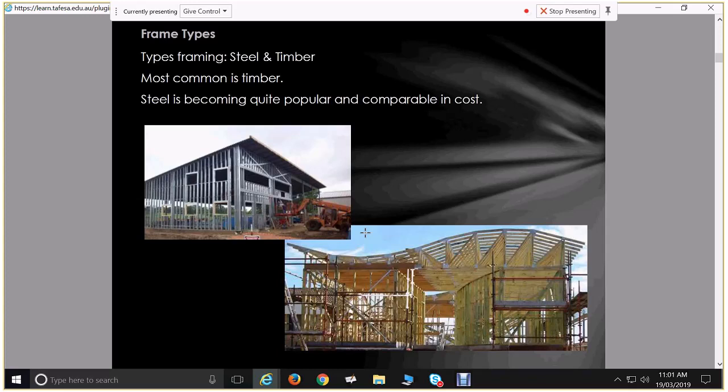So if we're prefabricating stuff in a factory, one of the limitations is we can't and we shouldn't go making modification decisions on site. Sometimes we can. And also it has to be transported. So the size of these elements, and then also they have to be lifted. If we're building a wall frame on the slab, and then we just tilt that up with 1 or 2 people, that's fairly simple, and then you put your temporary bracing in, and it's done. If you have to lift that wall frame off a truck, you have to be very careful with lifting that wall frame off a truck and not twisting it and things like that, and then that has to be handled into site. So not a huge amount of efficiencies from manufacturing in the factory.